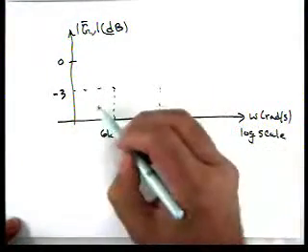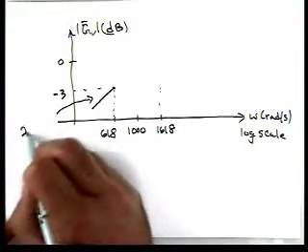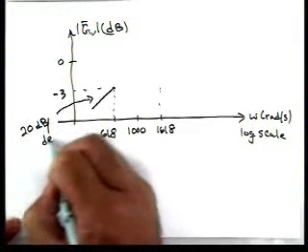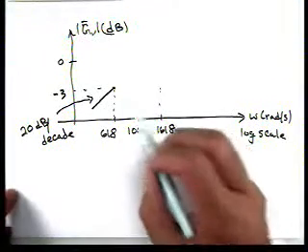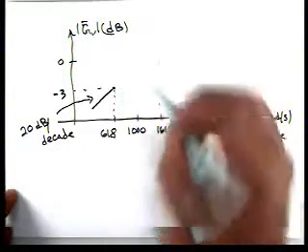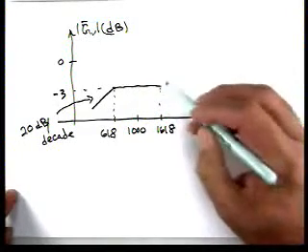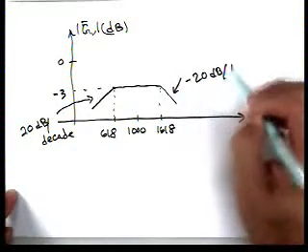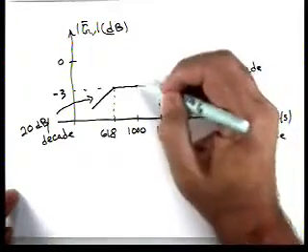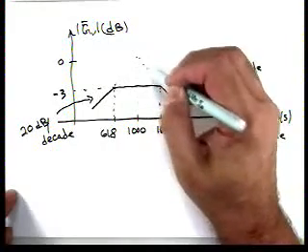So if we start off, from our simple zero at the origin, that would be a slope of 20 dB per decade. One of the poles turns on at 618, and it has a slope of minus 20 dB per decade. So it's going to give us a slope of 0 until we get to the other pole. When it turns on, we're going to go down at a slope of minus 20 dB per decade. Ideally, this would go right into 0 there. So this is our sketch of the magnitude.